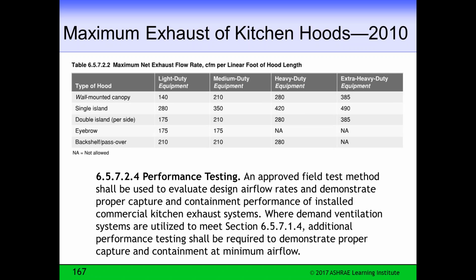So if you have an engineered and certified hood, this is the largest amount of air per linear foot we will allow you to suck out of it, because anytime you're sucking air out, you've got to make it up, and it's an energy user. Performance testing on hoods is a requirement, and it's the only requirement for performance testing we currently have in the mechanical section. The other sections are starting to populate some other performance testing, so this is the only one we've got so far.